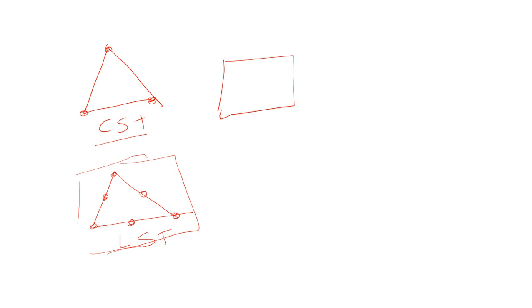Now we will discuss the derivation of shape functions for two-dimensional problems. For this we use the CST element, because it is easy, the constant strain triangular element. First we need to understand its coordinates.